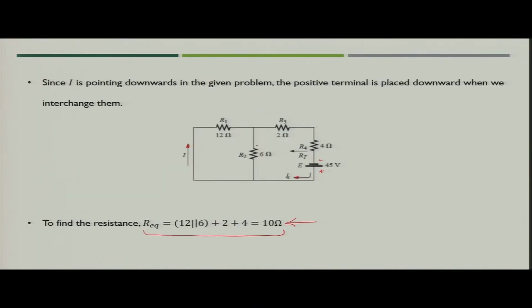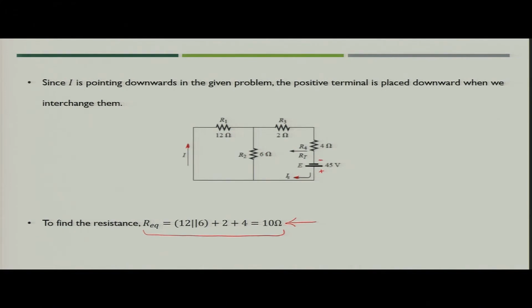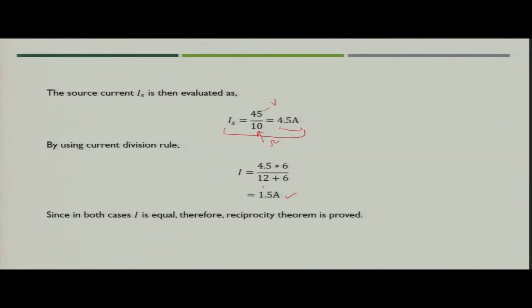So, you can see from here that you need to find out the value flowing in the short circuit segment. So, this would be the 12 ohm and 6 ohm. So, 12 ohm plus 6 ohm has come in the denominator, 6 ohm is the value here. So, we follow the current division rule and it will come out to be 1.5 ampere.